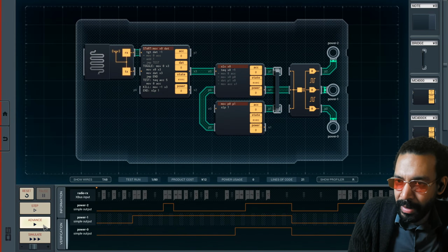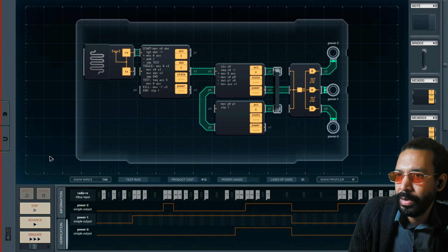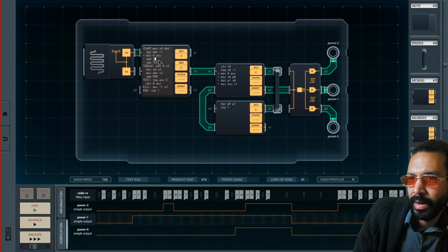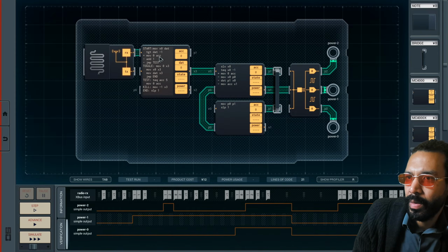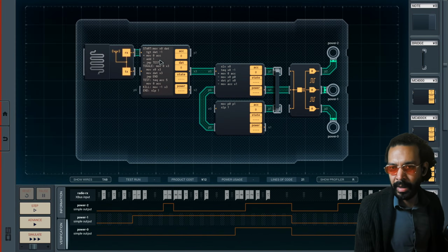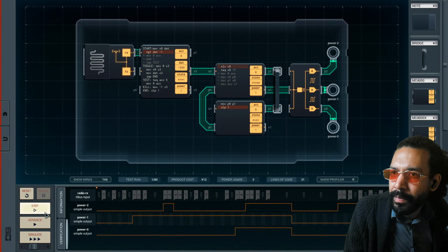Okay, so what's going on here? This chip here should be keeping track, and its accumulator should be keeping track of the elapsed time. So it is not even doing that. So move 0 to accumulator, add 1. That add 1 should be executing when it's like -1 or -999. So let's step through that line by line and see what's not happening.